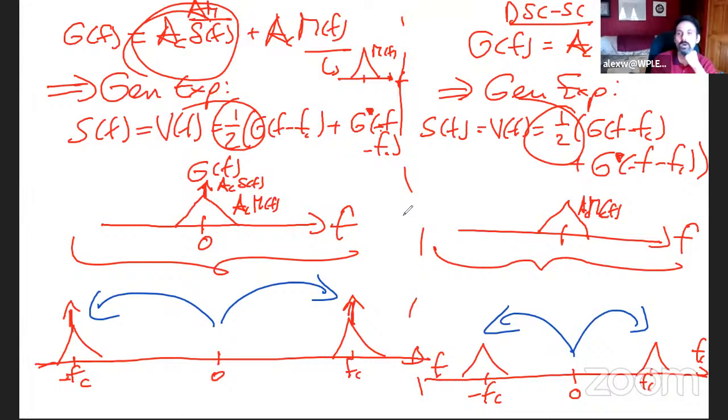So you might say, okay, so what, Wyglinski? Well, this is the so what. Carrier, right? It's that delta function that is the difference between AM and DSB-SC, is the fact that I have this delta here, and that delta is not present over yonder, right? So that's the difference between the two, okay? That's the difference between DSB-SC and AM, the lack of that delta function. That's good and bad. And you might say, how?